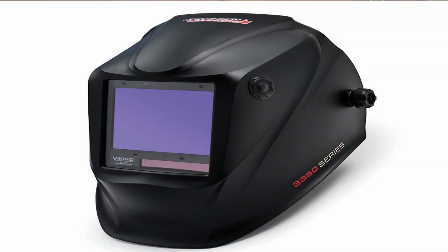And the hazard is exposure to UV or IR radiation, which can cause burns or welder's flash, leading to severe eye damage. Mitigation plan would include, number one, elimination. Use automated welding machines when possible. Engineering controls. Set up welding screens or curtains to protect nearby workers. Administrative controls would include to enforce safe distances between welding operations and other workers. And finally, PPE. Wear welding helmets with appropriate filtered lenses. Use safety goggles underneath if necessary.